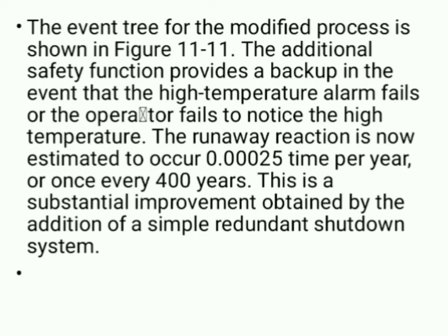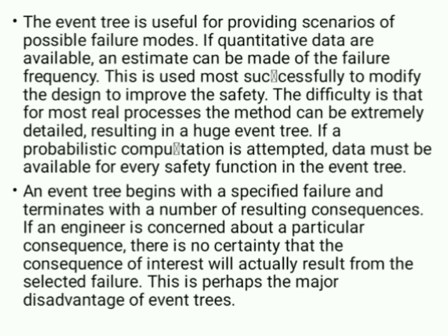Now the event tree is useful for providing the scenarios of possible failure modes. If quantitative data are available, an estimate can be made of the failure frequency. This is used most successfully to modify design to improve safety.